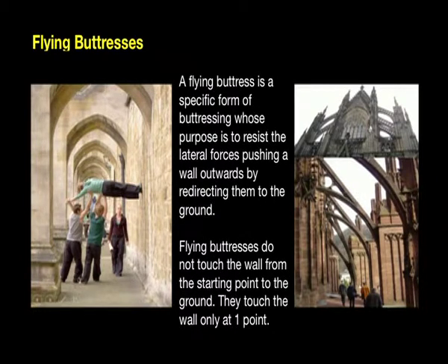Look at the pictures on the right. Here, the load on the pier is too immense because there is loading coming from the top. The top of the truss provides immense loading onto the piers, but the pier cannot take the load alone. So, a part of the load is being transferred to these sub piers, which are connected to the main piers by means of a flying buttress. Same is the case with these areas.